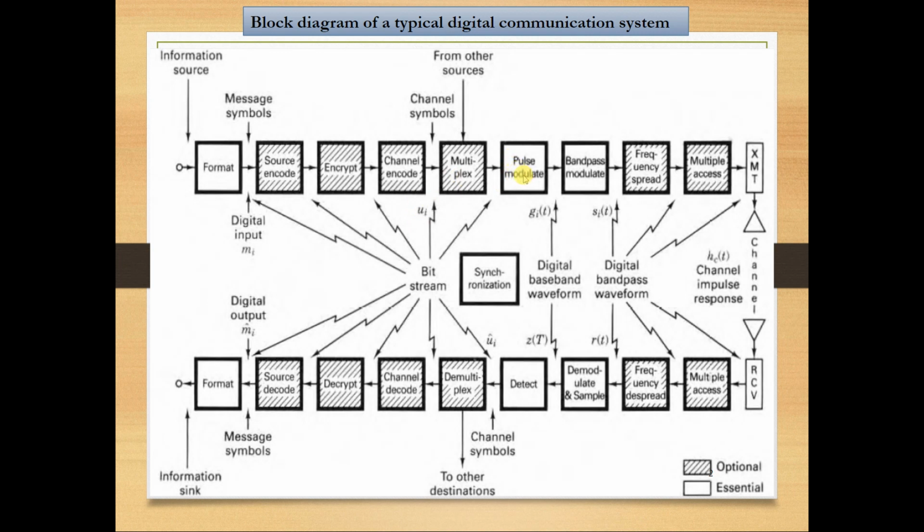But what shape of signals do we have to use? What determines that? What determines that is the property of the channel. Let's assume your channel is subject to distortion in time or frequency, or subject to synchronization errors or phase noise.